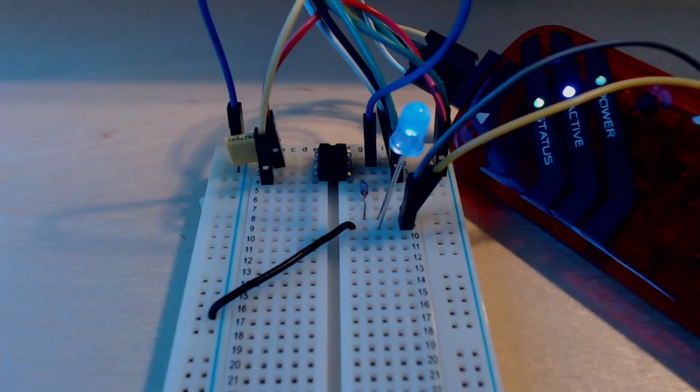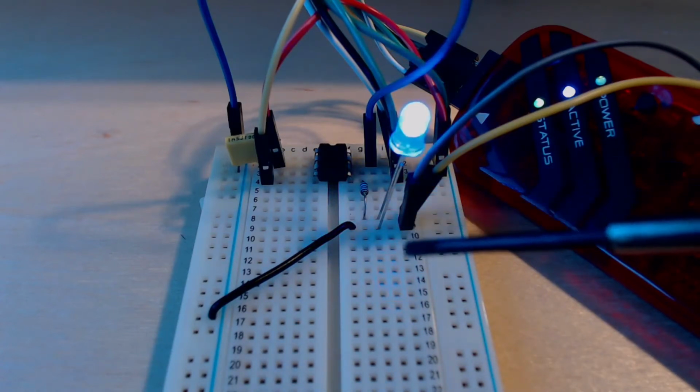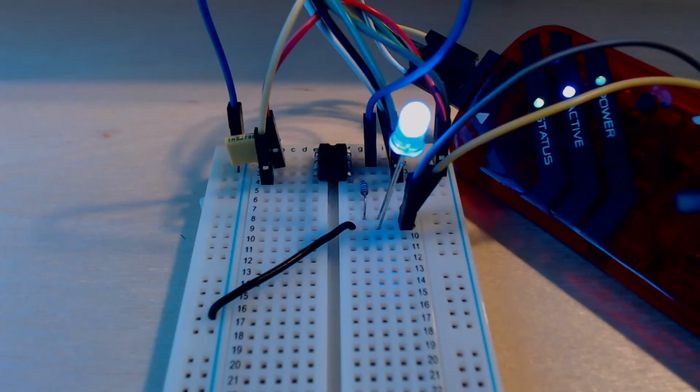Hi everyone. In this video, we'll be controlling the brightness of a single LED using a microcontroller. Our microcontroller is our reference good old PIC10F220, and we have a very simple circuit, which is just a good old blinky circuit basically. We have the 220 ohm resistor connected to the GP0 pin of our microcontroller. We have the LED, we have the PICkit to program and power the circuit. And that's pretty much it really.